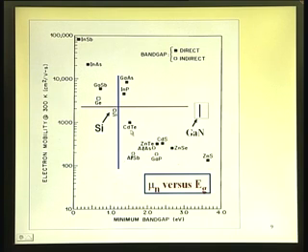Cadmium telluride is there, wide band gap larger than that of silicon, mobility lower than that of silicon. Cadmium sulfide, band gap larger than that of silicon, it is about 2.5 electron volt, and mobility much smaller. Electron mobility we are talking of, it is just about 300 or 350. Zinc telluride, band gap about 2.3, the pointer shows there, and the mobility is something like 300, 350, which is much smaller than that of silicon.